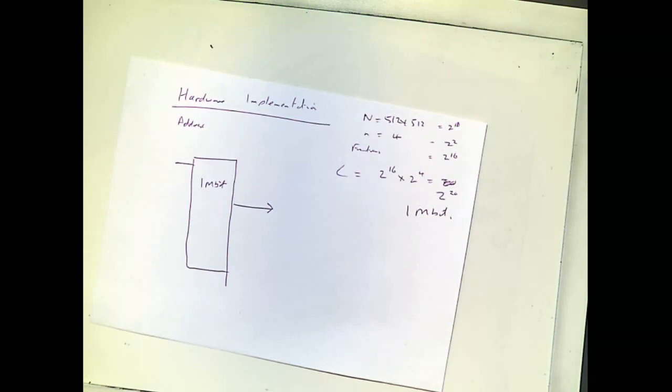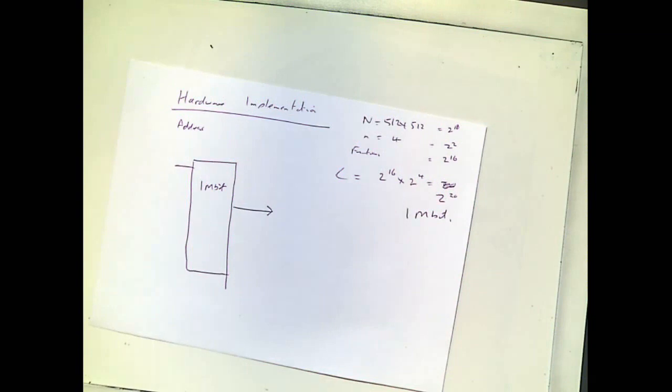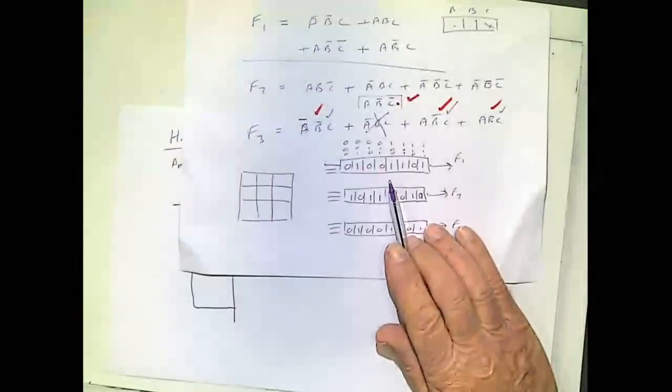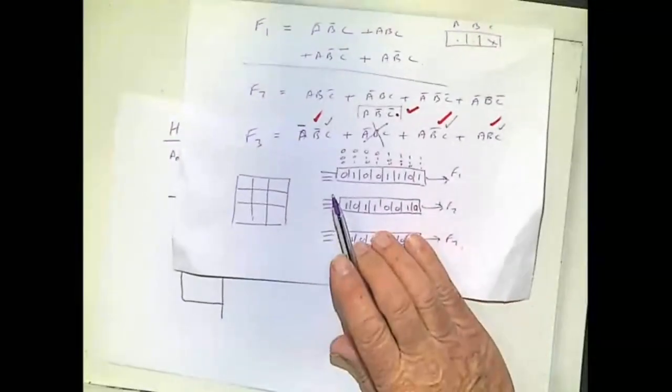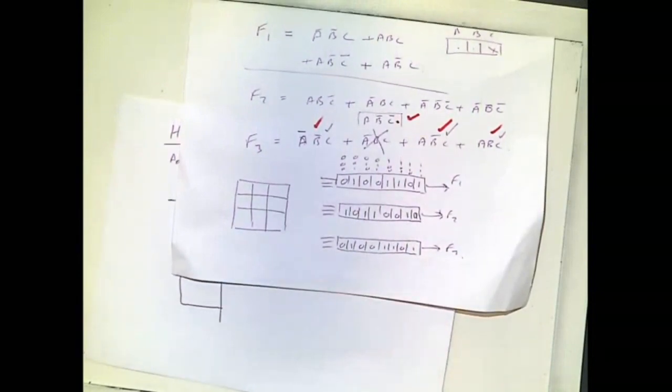Okay, back to first principles. If I have 4 bits, go to the 8 bits we're using here. Go back to that diagram. 8 bits, 3 address lines. 16 bits, how many address lines? 2 to the 4, so 4. 32 bits, 5.